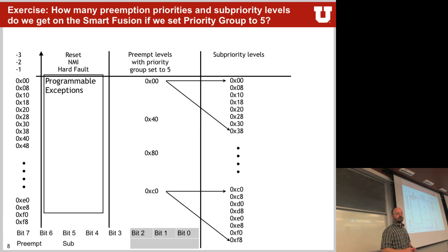Does sub-priority only matter when there are many interrupts from the same priority group? Yes. Instead of preempting each other, when there are multiple interrupts pending, they will go through this order depending on the different priority, and they will be handled one after the other. We'll look at that in a second, on how tail chaining and other things happen.